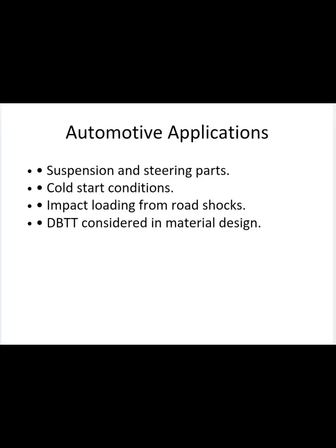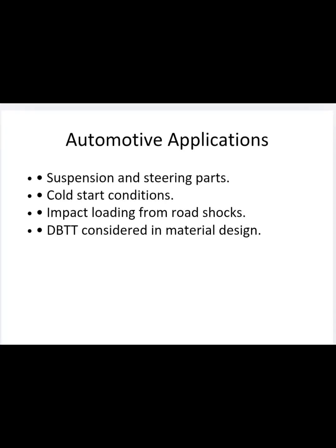Next one is automotive applications. In the automotive industry, components such as suspension and steering parts may experience impact loading. During cold conditions, these components may operate near the DBTT. If the material becomes brittle, sudden fracture can occur during impact, such as hitting a pothole.